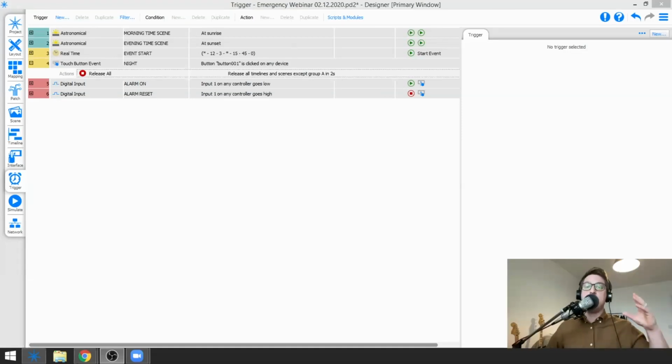As I said, we never release timelines within Pharos unless you physically tell them to release. So, if I start timeline number 1, that plays, and if I then start timeline number 2, that will then play, but timeline 1 will then sit underneath it in the stack. With high priorities, basically what happens is they just jump to the top of that stack. And if you have any timelines playing previously, once you release that highest priority timeline at the top of the stack, it will then obviously reveal back to whatever's underneath of it.